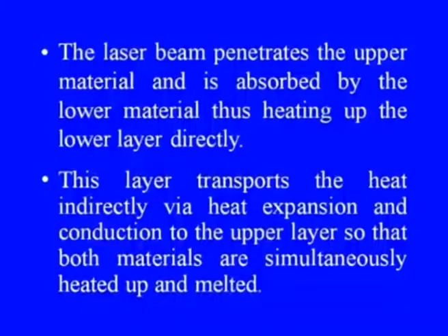The laser beam penetrates, in this case, the upper material and is absorbed by the lower material, thus heating up the lower layer directly, as we have seen in the figure. This layer transports the heat indirectly via heat expansion and conduction to the upper layer, so that both materials are simultaneously heated up and melted.